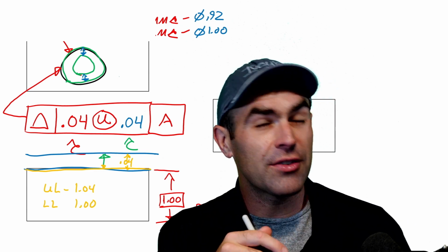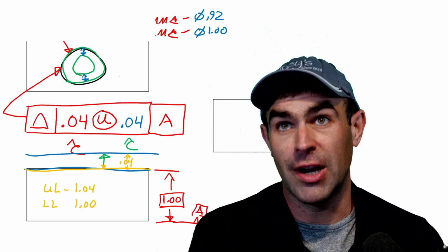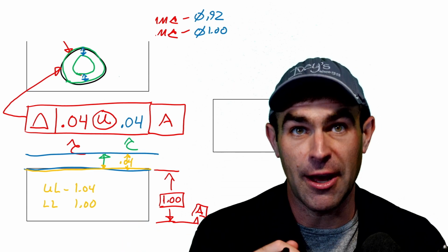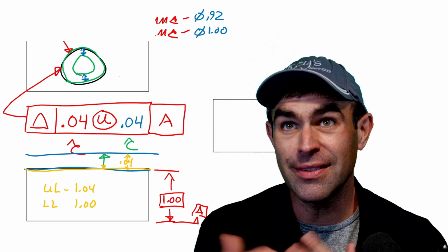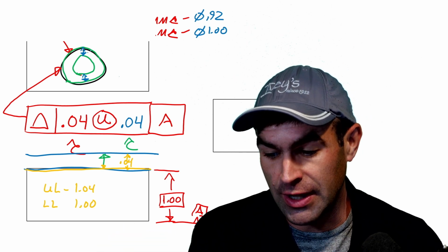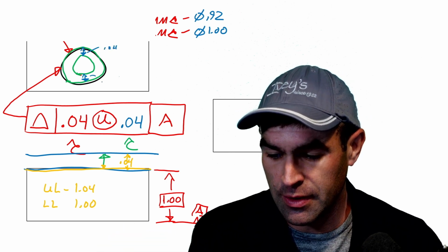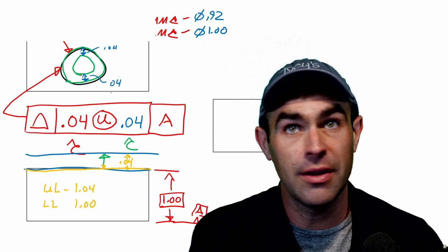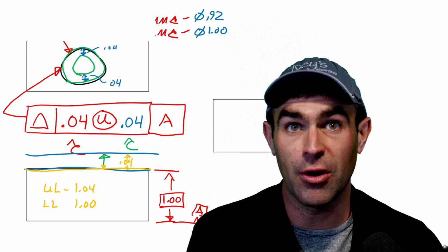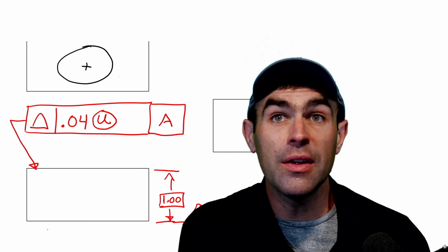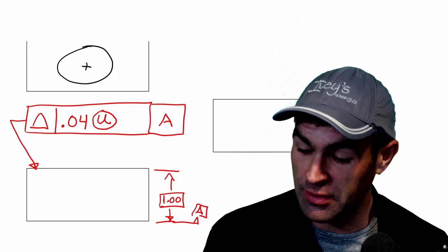But it's one of those things, like, I hope you don't have to memorize this. You should be able to just sketch it out. As long as you know which way the profile applies, you'll be good. You can just draw a little sketch here and be like, okay, that's 40. That's 40. Done, right? Total of 80. Subtract it from the basic dimension. We're all set.